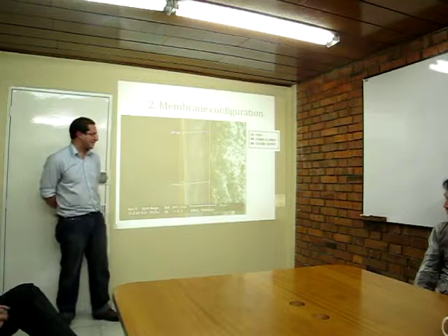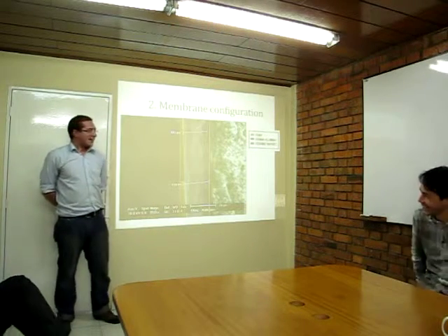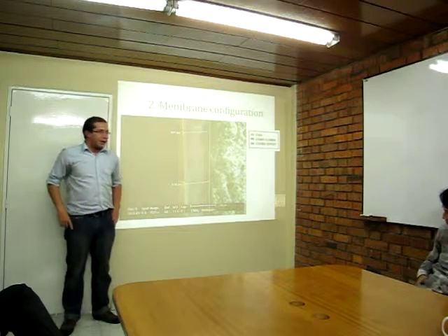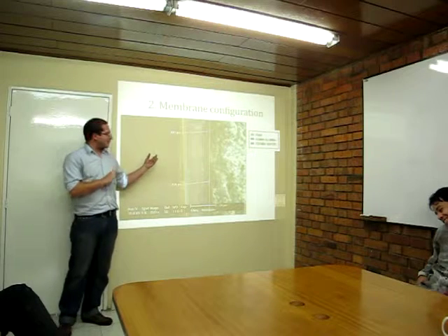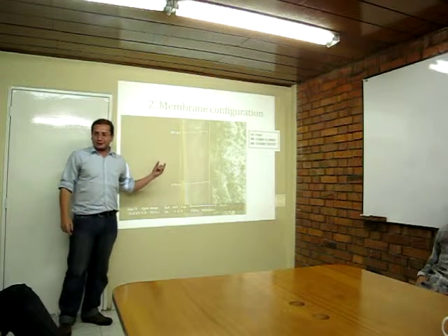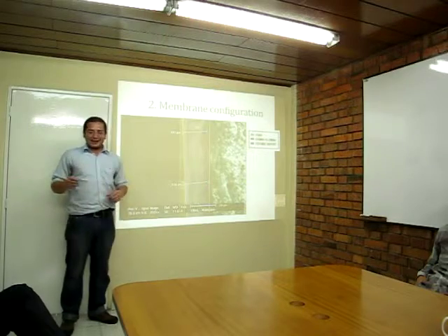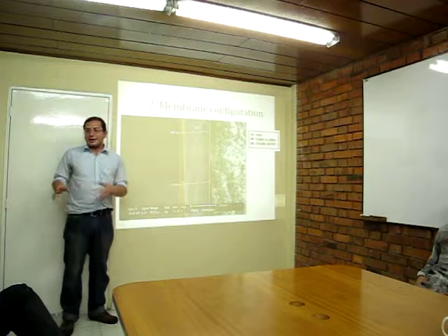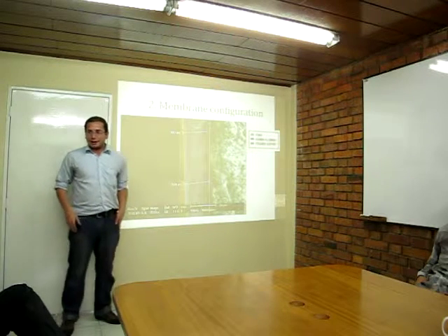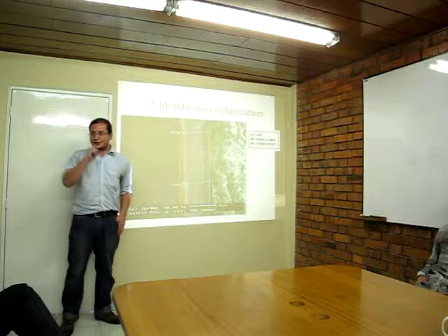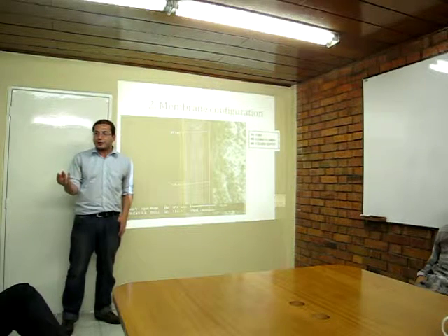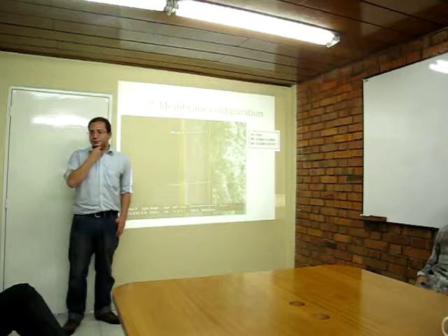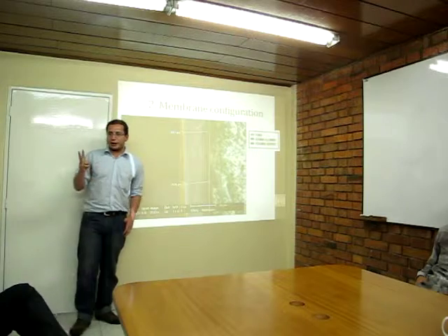Very good question, Professor. This is a result of the investigation, because this technique is called dip coating. You require calcination for this, more or less. What temperature for this calcination? No, it is not calcination, but you can cure. Yes, cure at 40 degrees for 3 hours.